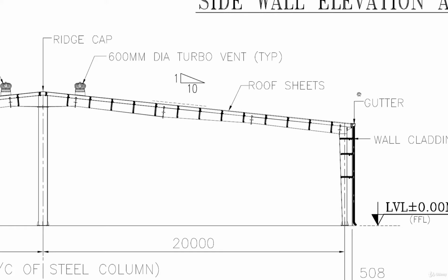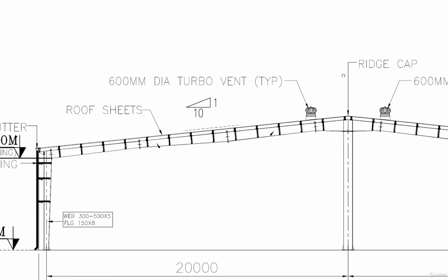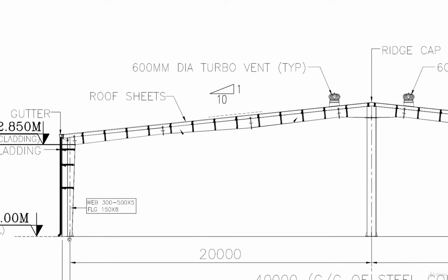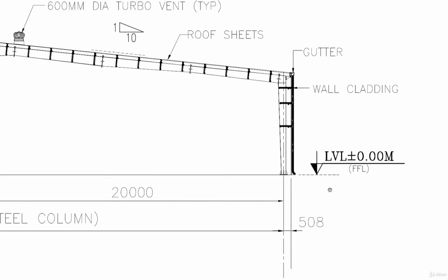That is, the bending moment is maximum here on the top, and then it comes to the bottom here, and then again it goes to the top here, and then again to the bottom, and then again to the top, and it reduces to 0 at the bottom. Why does it reduce to 0? Because the bottom conditions of PB sheds are preferably pinned. It can be fixed, but in my experience I have not seen a PB structure which is fixed at the bottom. It is a very rare case. So most of the time the end supporting conditions are pinned.